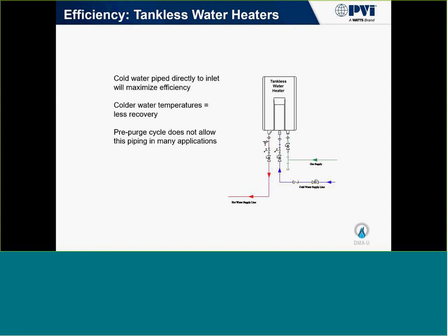But one thing to be said of it is tankless water heaters will sacrifice hot water output in order to maintain temperature. The incoming water temperature is very important to these. So the efficiencies you're going to get out of a tankless water heater, or the performance of a tankless water heater, are going to be drastically different in colder weather versus warmer weather.